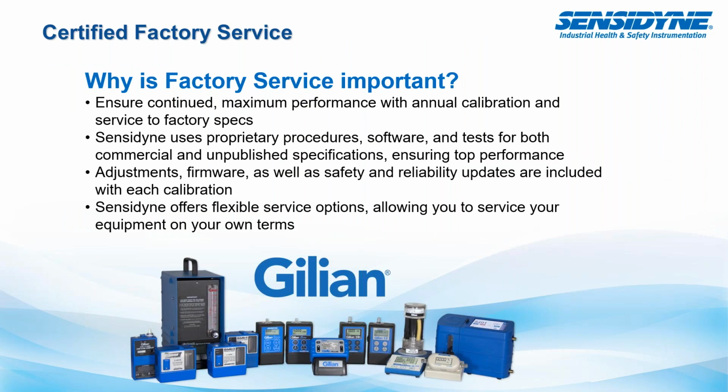Now I wanted to go back to why it's important to have certified factory service. I can't stress this enough. I showed you early on in the presentation that there are a lot of different parts, components, and moving innards that can eventually wear out and lead to failure. These can include, as I mentioned, the inlet filter, and different seals, gaskets, and O-rings. The best way to make sure you have a tight seal and consistent performance is to have it serviced on a regular basis to perform to specification.